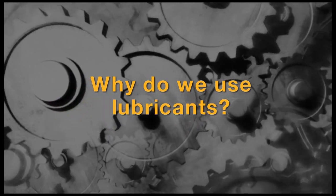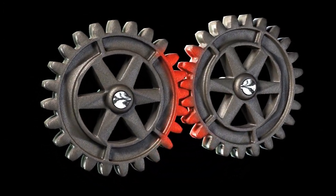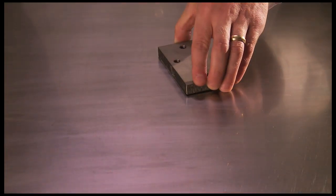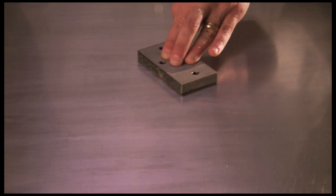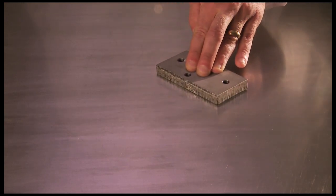So why do we use lubricants? Some of the primary functions of lubricants are to reduce friction and to dissipate heat. You'll find friction whenever two surfaces rub together. Even if the surfaces look flush and smooth, similar to what you would find on bearings and gears, you would still have tiny asperities causing friction.